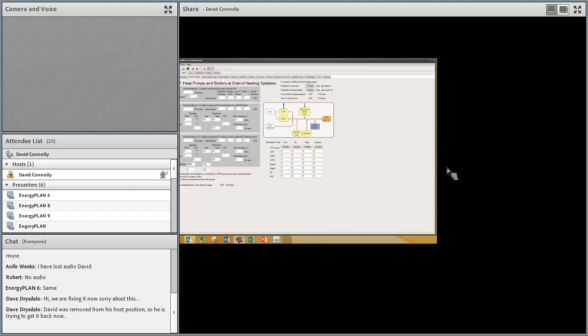Over in the fuel distribution on the right hand side, I decide what type of fuel do those power plants use. This is a ratio between the different fuels that the power plants can consume. So in other words, in PP, which is the capacity I've just entered, if I enter in 1 here, for example, then all of the fuel that the power plants use will be natural gas. If I enter another 1 under coal, then 50% of the fuel will be coal and 50% of the fuel will be natural gas. In this example, just to keep things simple, I'm going to use nothing but natural gas. So I'm just going to put a 1 under natural gas, which basically tells the model that 100% of the fuel that the power plants consume should be natural gas.